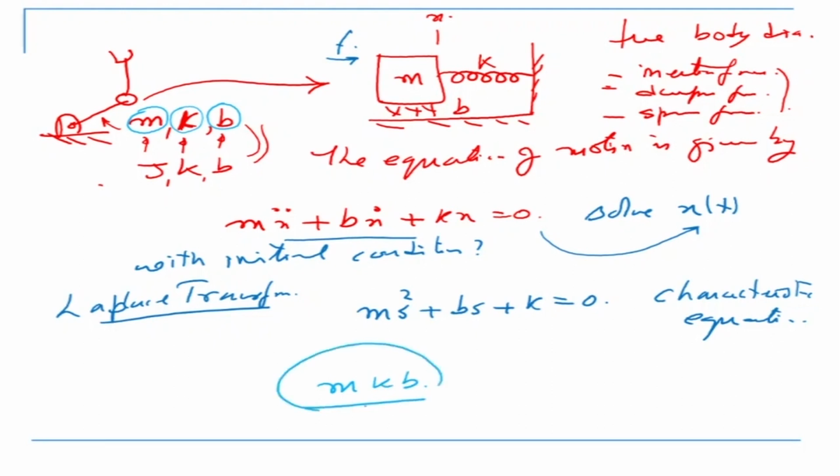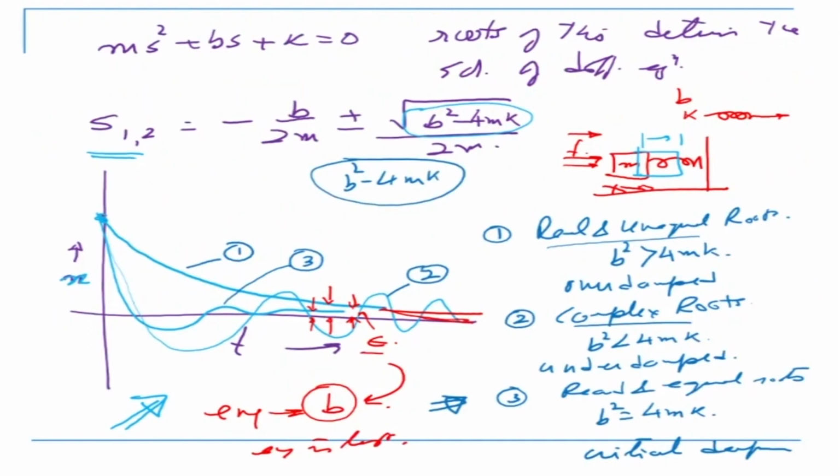So this gives us the basic idea that we are using the spring mass damper system to model the motion of a link. Depending on the values of m, b, k, we can choose what kind of behavior it has out of these three, and we have said that we choose the behavior where the system should be critically damped. We always consider this condition.